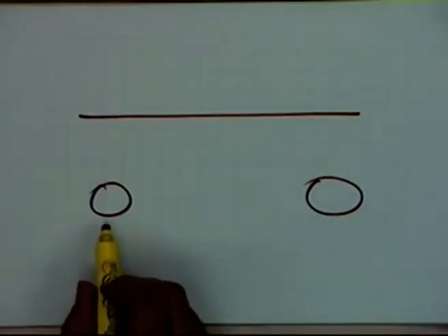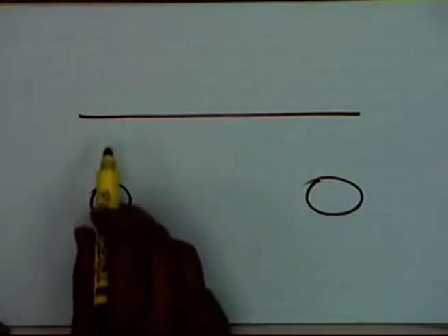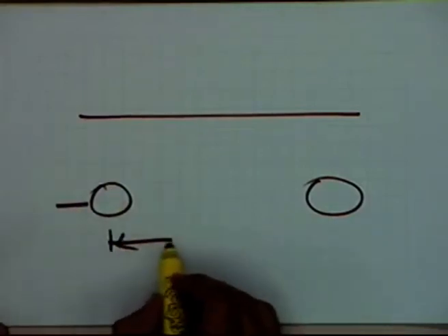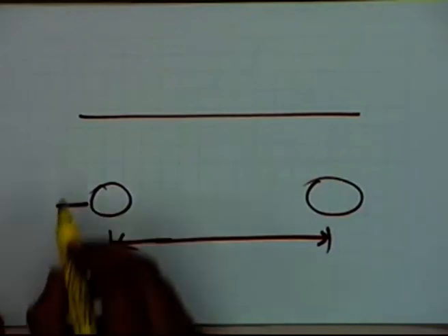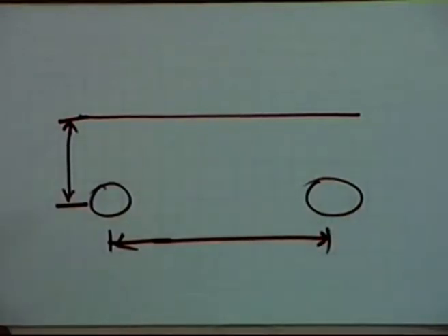In this situation also, again, you will have to decide what will be the depth up to which you have to lay down the pipe, what will be the spacing between the pipes, and what size of the pipe has to be used. So these are some of the parameters which will be needed to design the system, how the system should be laid out, and that will also be a function of what type of crops you are utilizing.